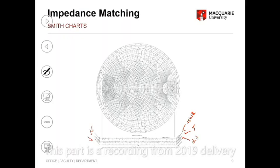But what I'm trying to say is that the Smith chart will give you a big insight into the circuit. Just by reading off a point, you can probably say what the reflection coefficient is, what the impedance is, what the admittance is, because you can switch between all that. Now with the tools you can switch between them because they'll do it for you. Previously we didn't have those tools, right? I mean the AWR, CAD tools. So that's the use of the Smith chart.